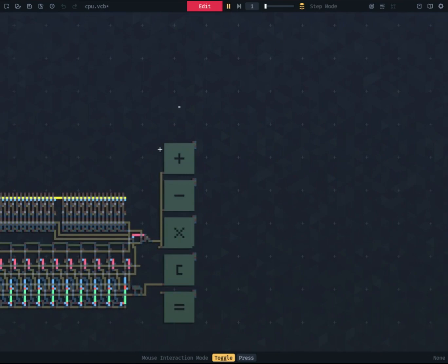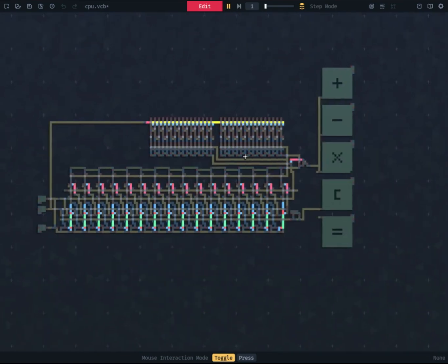You have the pause simulation, which is very useful when you want to debug things. For example, you see something that isn't working right, and if you launch, for example, I clicked on this LED, on this latch, and if you click on this, it will just go to every tick when you ask it to. It's very useful for debugging.